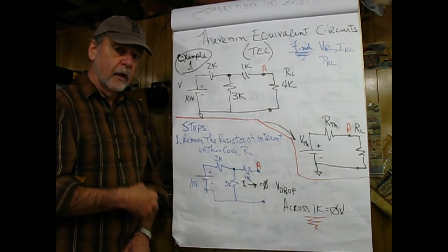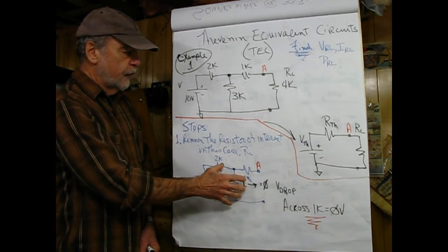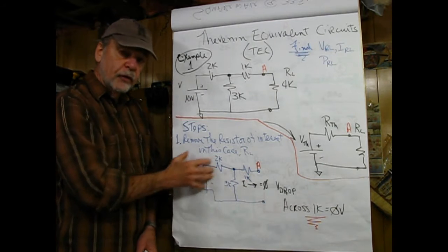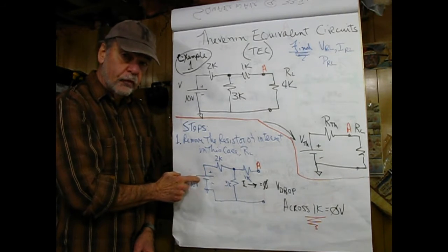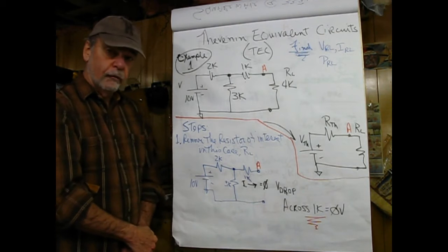That's the Thevenin equivalent voltage that's going to be feeding this circuit. So VTH is going to be representative of how these resistors and the source are affected. So obviously it'll be a lower voltage.